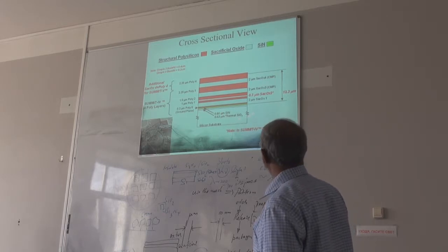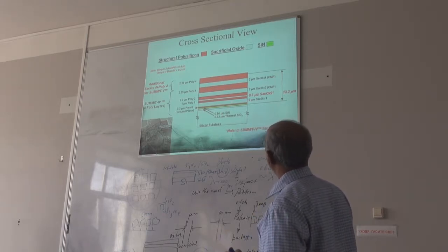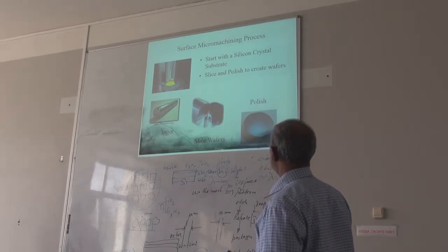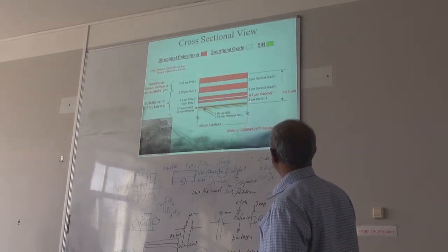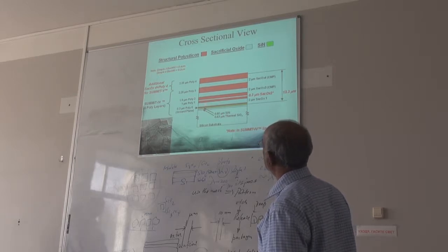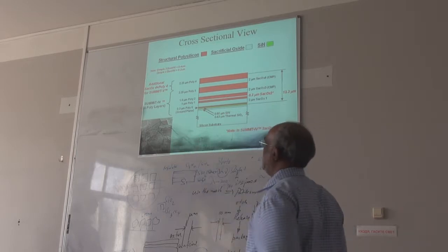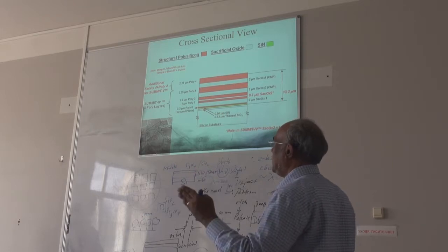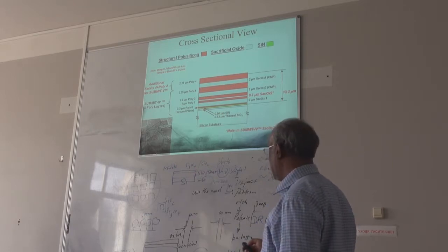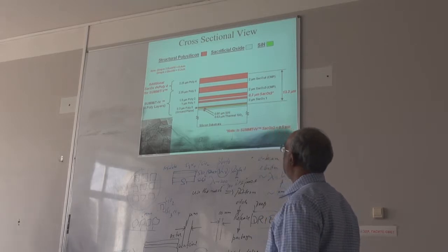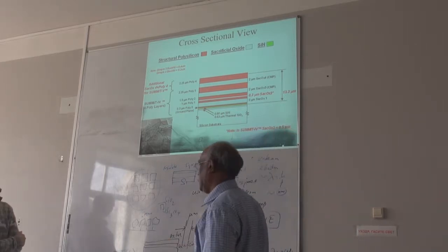If you want to continue, again you can put another sacrificial layer and then another functional layer, polycrystalline, then another sacrificial layer, and you can repeat any time you need. So at the end you can etch it and release it. Then you can make some structures like these things. So we will get into details like this.